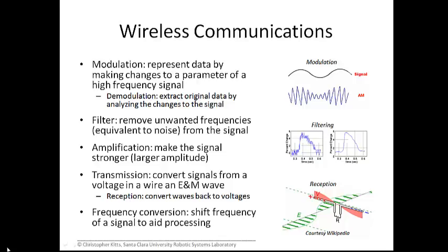Another thing we're going to be doing is filtering. We're going to do that in order to get rid of unwanted frequencies. Some of those frequencies are going to be injected in the communication path itself. It would be noise from other sources of radio emissions, but we also will be filtering out signals that we create through the engineering of the communications equipment and system itself. And those frequencies are a natural byproduct of the process through which we go to modulate our waves, but we just don't need them ultimately for the receive process.